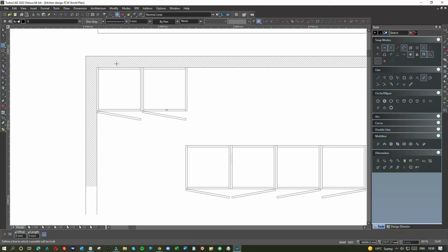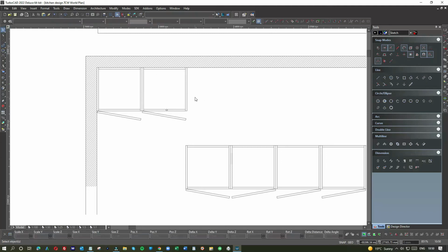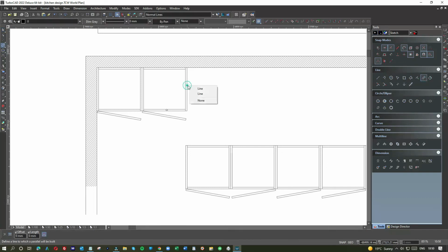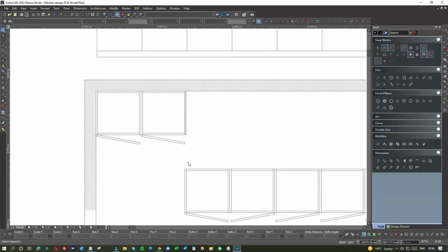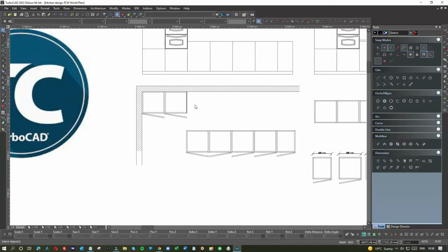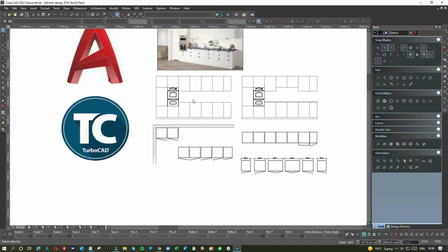Right, so now what I've got to do is tab. The side panel is 12mm. So tab 1, 2. What that means then is when I look at the side of this unit from here, looking in, I'm going to see the appropriate colour or the appropriate finish. If everything here is white gloss, then that'll be white gloss.